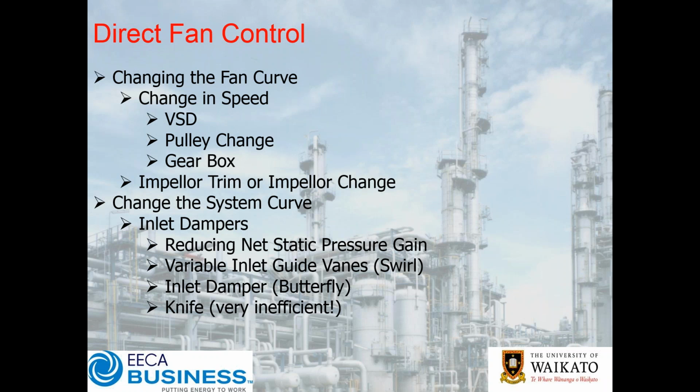And then based on what you've currently got, you can infer with some decent analysis what you might need, and it could be the next size impeller up, either in width or diameter or both. Now if you're unfortunate, you could already have the biggest impeller available for your fan size, in which case you will need to go up to a next sized fan housing and so forth.